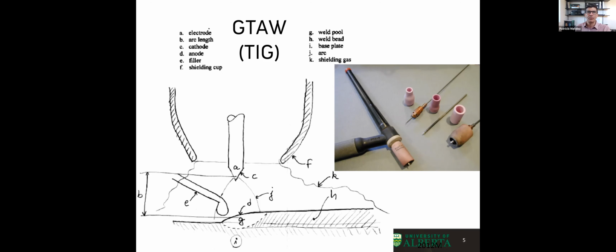In arc processes, polarity matters. So typically TIG welding, gas tungsten arc welding, is run at constant current, which means the machine will give me more or less the same amount of current, say 125 amps. And if I move the electrode farther or closer, it's gonna be 125 amps. The voltage is going to change, but the amps are gonna be more or less constant.